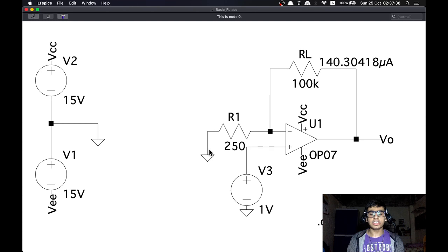Here too, the relationship of Vin and IL, which was supposed to be IL is equal to Vin by R, where R is this input resistance, has been proven false. So, what we can conclude is that although these circuits are theoretically verified, these do not work in practice. Here we need to use actual V2I converters which are made industrially, and homebrew circuits do not work.